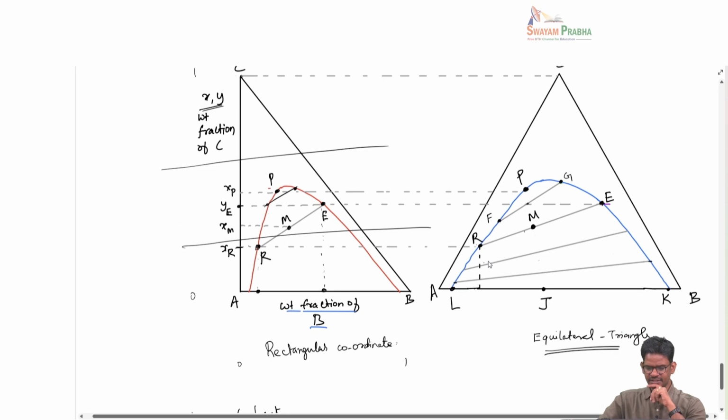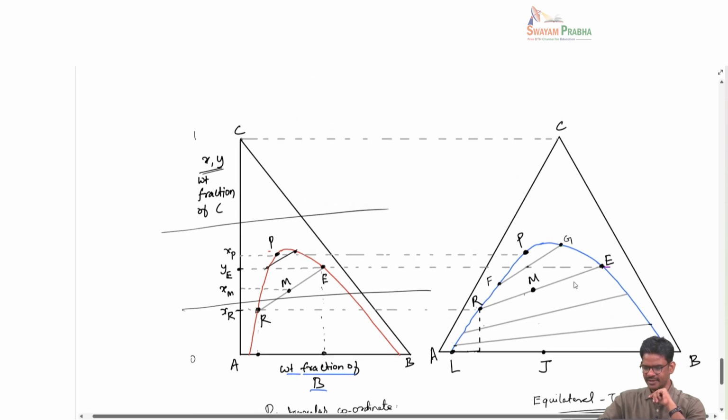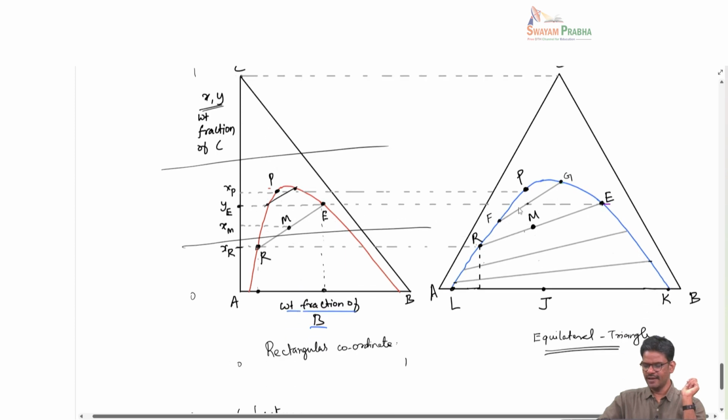And finally, I mentioned that this ternary diagram can also be mapped into a rectangular triangular diagram, so that it has an advantage that I can readjust the composition ranges to different levels of C. I can go to very high C or I can keep it at a very low C, and every tie line that is here is mapped here, you do not lose this information of tie line, okay.